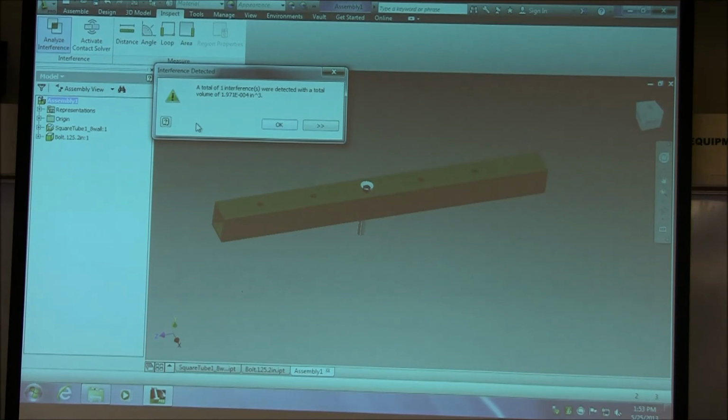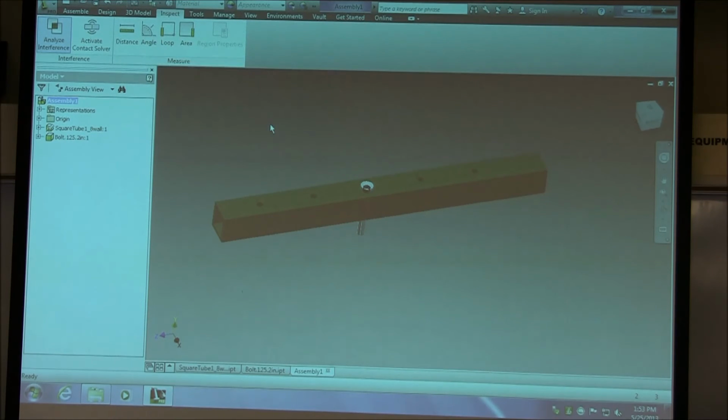And you see now, I hope, these two little red green looking things right here? That's telling me that there's interference between the two parts. I made something wrong and there's overlap. If I actually try and do it exactly to the specifications I have here, it's going to be wrong. I already kind of know what I did wrong because I did it wrong on purpose, but this can help you identify problems. If you have a massive robot and you're trying to figure out whether it will all actually fit together, this can really help you out and figure out the problem areas too.